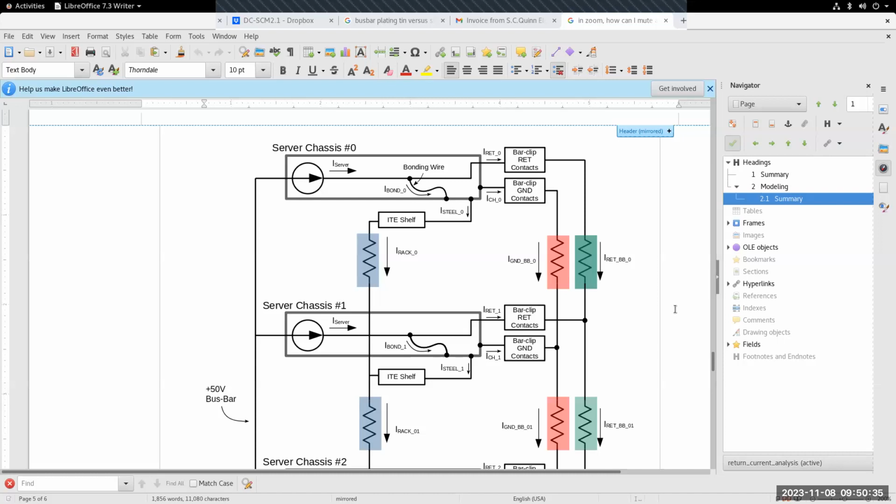Joseph, this is Mike Wingard with Amphenol. One other interesting point that you might want to include is the ground path in the vertical bus bar, at least in our bus bars, is actually aluminum, not copper. Matte tin over nickel, aluminum. Yep, I thought about that, right? The aluminum is about half the conductivity of copper, but there's two of them. Yes. And they're big. They're big and thick, right?